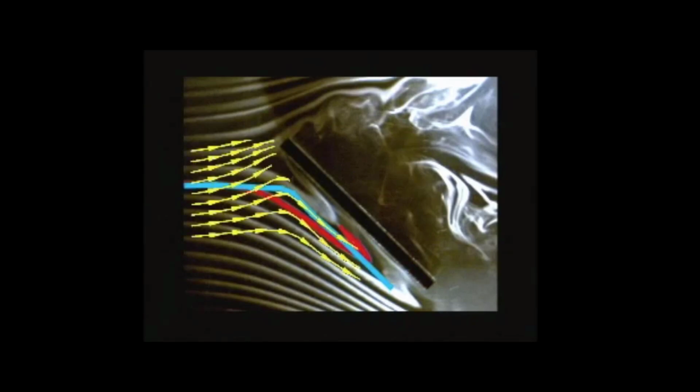In unsteady flows, streamlines, streak lines, and path lines can be quite different. Here, the unsteady flow over a rotating plate is shown. When the flow is observed at an instant when the plate angle is the same as in the previous steady flow, we can see that all three lines differ. The streak lines and path lines, which developed over a time history while the plate was rotating, differ from the instantaneous streamlines.